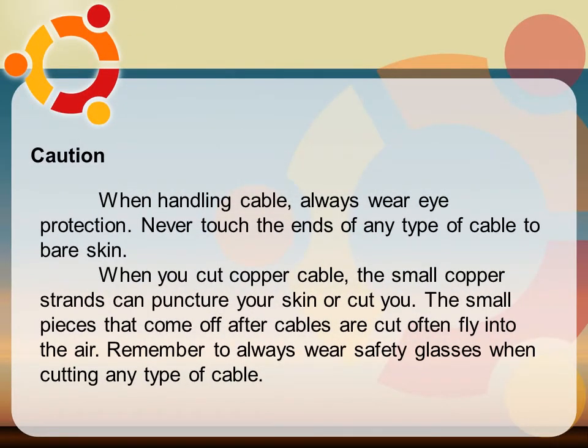Caution! When handling cable, always wear eye protection. Never touch the ends of any type of cable to bare skin. And when you cut copper cable, the small copper strands can puncture your skin or can cut you. The small pieces that come off after cables are cut often fly into the air. And remember to always wear safety glasses when cutting any type of cable.